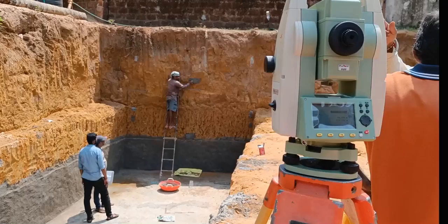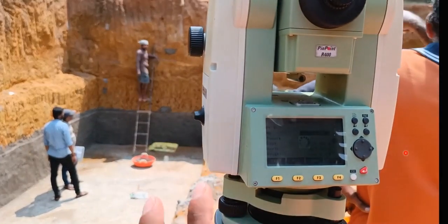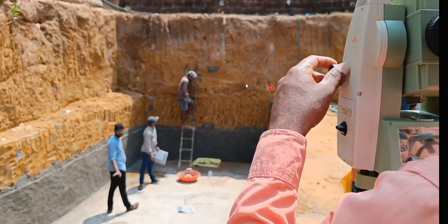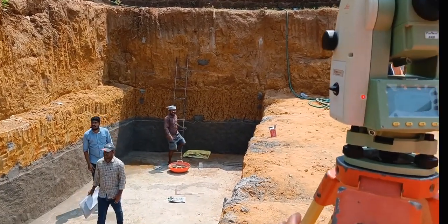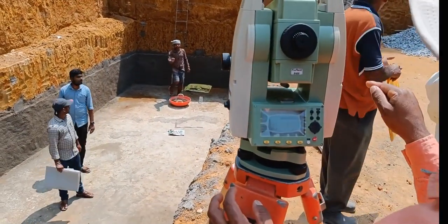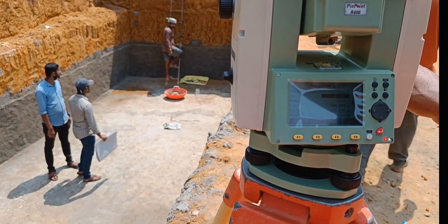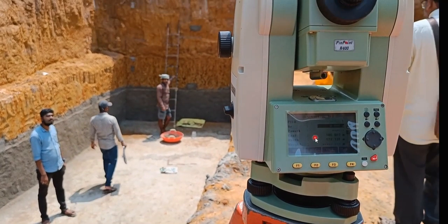Yeah, we'll go back. So you can see a lot of numbers coming here. This is the input you have given to the total station instrument. So this is processing. Once it is processed, he'll project it there, and with this you can set the laser. You can see some numbers written here, right? 100.003, you can see it, 527, see 100.003. So in this way, whatever we wanted, exactly how to input it, you can see here east, north, and what is the height, everything will be done here.